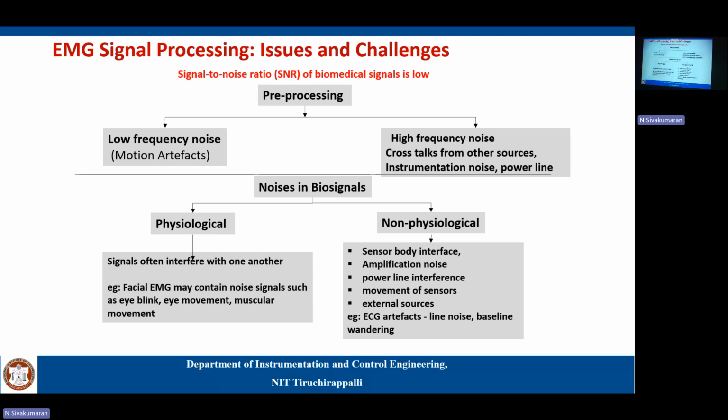Right now, when I place my electrodes on the forehead, I also get signals from muscles. We know muscle signals lie up to 150 Hz or 250 Hz. How do we remove that? Now you see the overlap in frequency. Here up to 70 Hz, there up to 150 Hz. If you use a band pass filter, this band pass filter also removes your EEG, right?